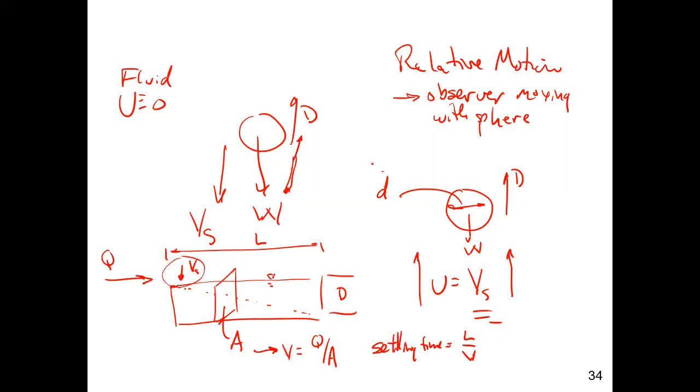So basically, you can identify which size particles you can settle out. Typically, we can get out sands, maybe fine sands. But particles smaller than that will take days to weeks. Clays will take months. And so when we have finer particles, we have other ways of settling. This is just gravity settling in this case. So are there any questions?